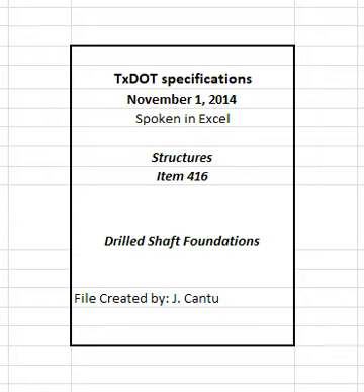Use a cleanout bucket if material is too large to be picked up with an airlift. Reprocess the hole with the auger as directed if concrete placement is not started within 4 hours of the completion of the shaft excavation. Then clean the bottom with an airlift or cleanout bucket, and check the slurry at the bottom of the hole for compliance with the slurry requirements of Article 416.2, Materials.